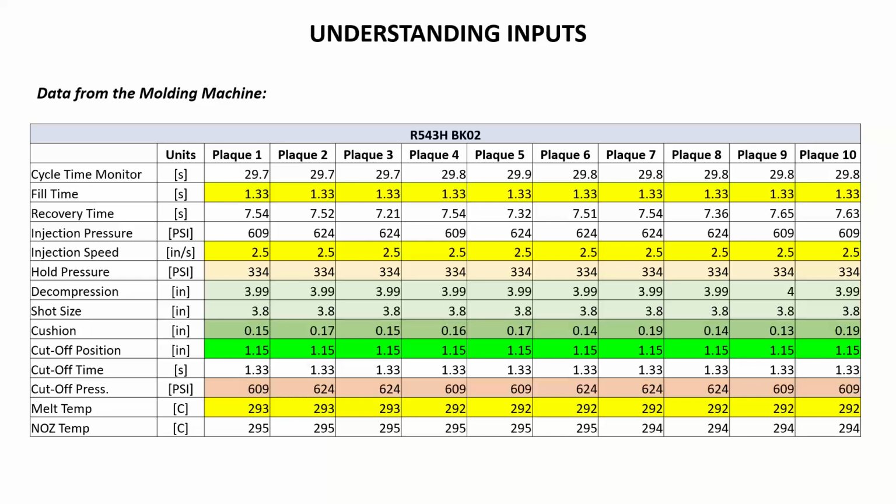Fill time. Now, fill time in simulation means the time that it takes to fill the cavity completely. But we don't know when that happens inside an actual mold. What we do know is the fill time that it takes until you get to the transfer point. That's our fill time coming from the machine. So they mean different things depending on your context. So we need to be careful about our definitions when we start comparing an analysis to what was happening at the press.